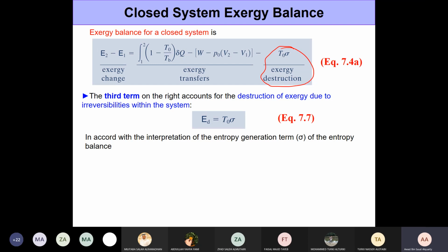Now, coming back to the question of can exergy be destroyed, or why is exergy being destroyed? Well, as we said, exergy and entropy are quantities which are not conserved, right? So whenever a system is going through an irreversible process, there is some amount of energy that just goes into that process, whether it's friction or heat transfer over a finite temperature difference. You lose some energy to that. There is some energy that's lost in the irreversible process.